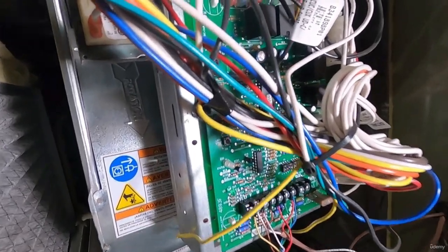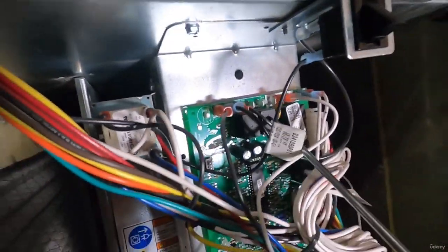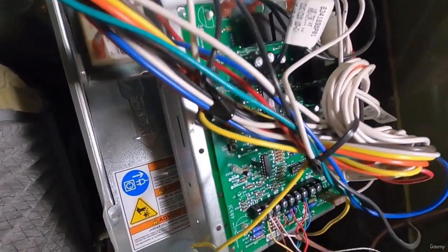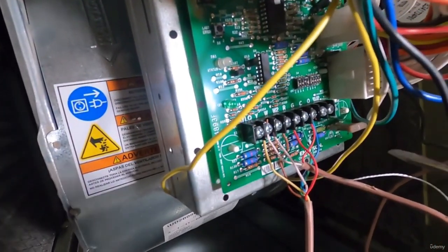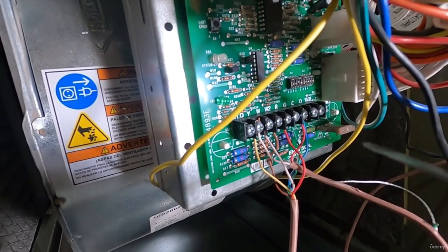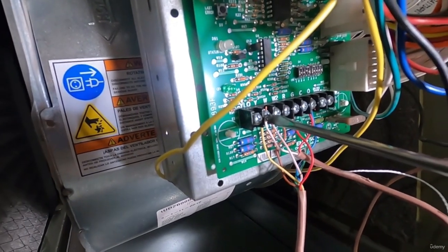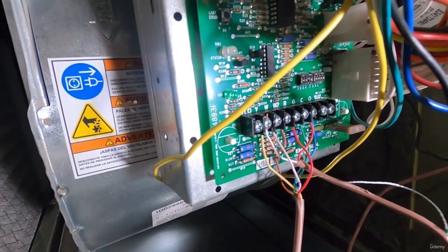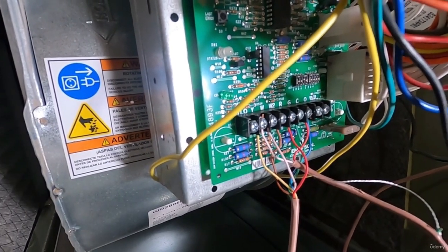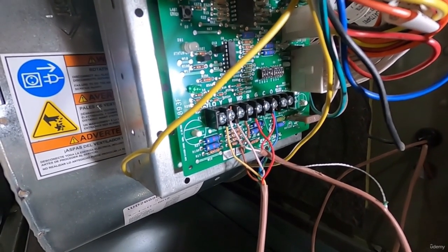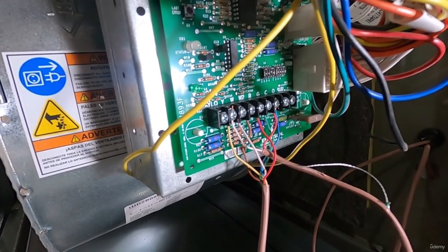in the cooling mode. And you got a lot of relays, and one of them is for the blower motor to turn that on. And then when you terminate power at the thermostat, when you shut it off or when it's satisfied, power is going to disconnect from the Y, and the air conditioner, the condenser, will shut off right away, and the fan will probably continue to blow just for a little while longer, kind of get rid of that remaining coolness.